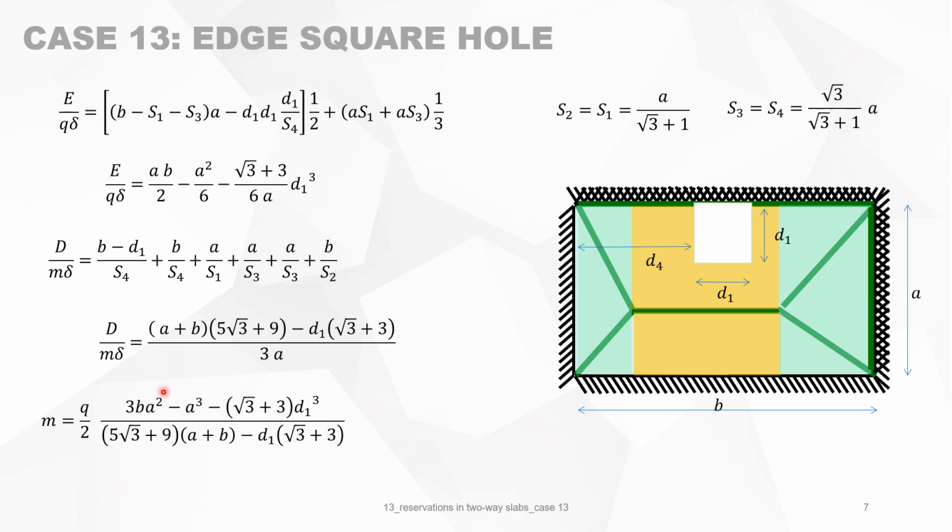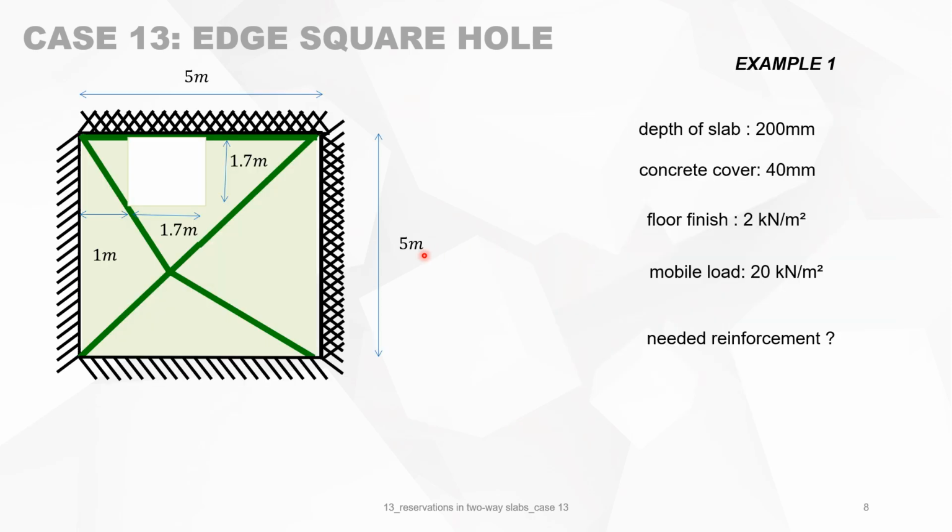Notice that this formula is only dependent on alpha and on D1, alpha or alpha 1, only dependent on the size of the flap and the size of the reservation. It is independent of D4. So now there's a danger in it because you can use this formula not knowing that it's not valid. You always have to check D4. The different elements that you got, you must always check that it fulfills D4. You will see to it just right now.